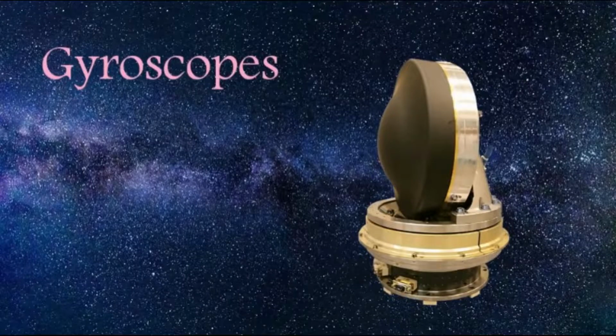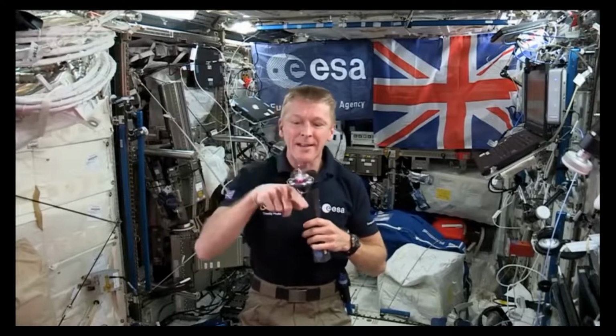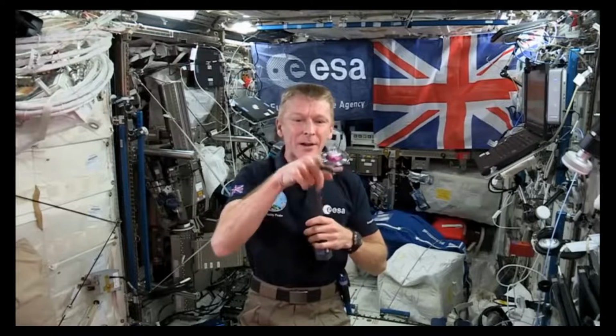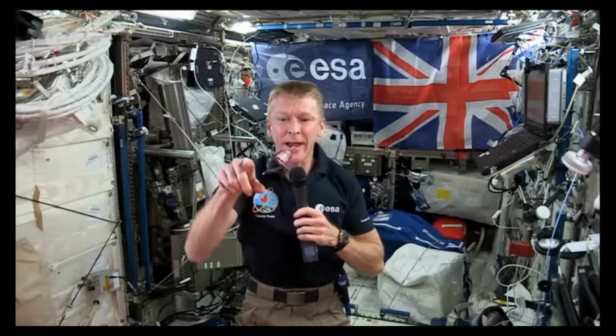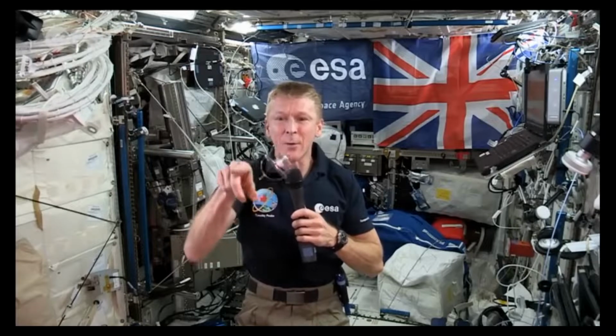Gyroscopes can determine attitude and changes without needing to look out of the window. The simplest type of gyroscope is a spinning mass. 2 basic principles of gyros make them useful as attitude sensors. With no torques, their angular momentum is conserved, so they always point the same direction, and with a torque applied, they precess in a predictable direction and amount.